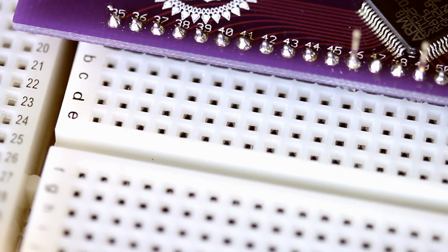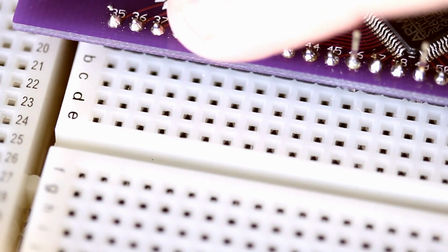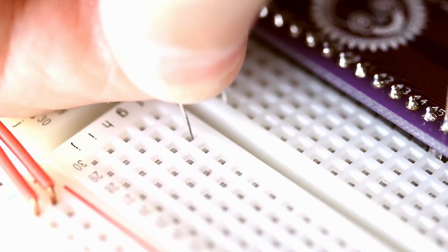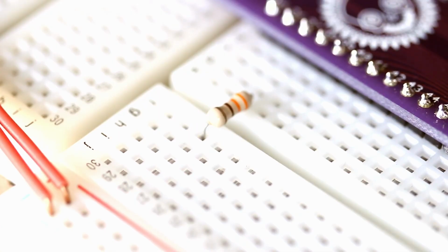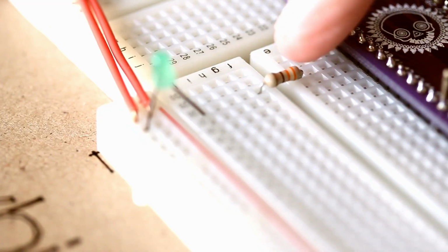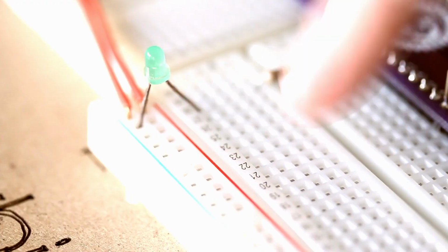Let's get started by connecting the LED to port C, pin 6. And that's on the pin number 37. Insert the 330 ohm resistor across the two tie strips, and then the LED with the flat side towards the ground. So from pin 37, we have a 330 ohm resistor to an LED that is connected to ground.